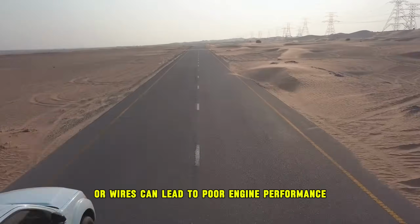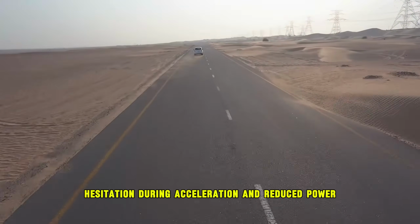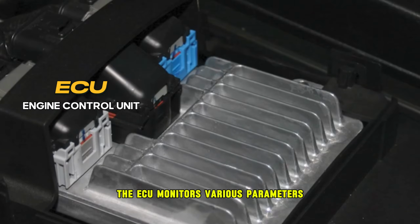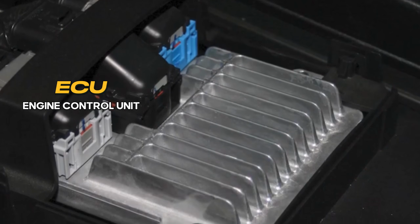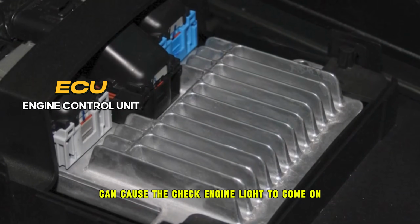Faulty spark plugs or wires can lead to poor engine performance, including rough idling, hesitation during acceleration, and reduced power. The ECU monitors various parameters to ensure the engine is running smoothly. Deviations from the expected performance can cause the check engine light to come on.